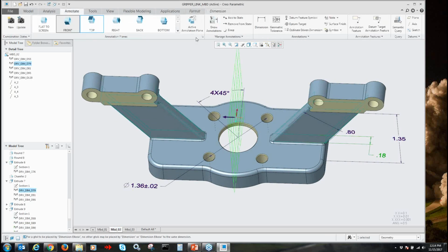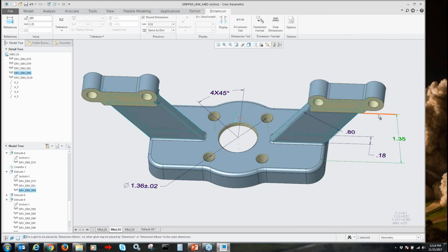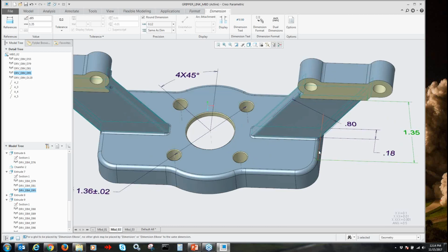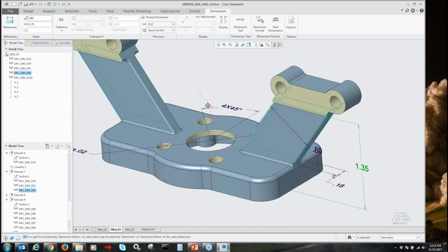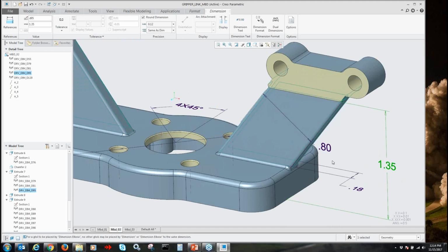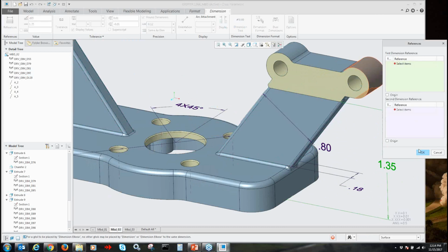But just real quickly, you should be able to just highlight a dimension. And I should have the ability with my notes here to go in and right-click. So when I right-click on the Edit Lines portion here, you should be able to go in and you can edit the definition of those dimensions. We can erase witness lines. You can insert a jog or a break. And then you can modify where the dimension origin is going to be for those dimensions in the process there. So you can see how it's kind of highlighting here and it's showing you the extension here. So I can bring this out. I can use the shift button and attach it to different walls as well. So to make sure that I'm calling these out in the right locations each time and making sure that those references are spelled out properly here.